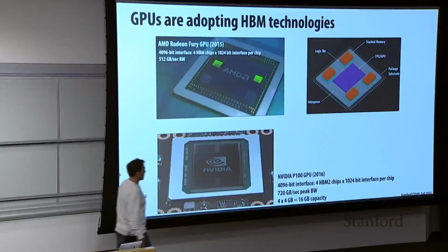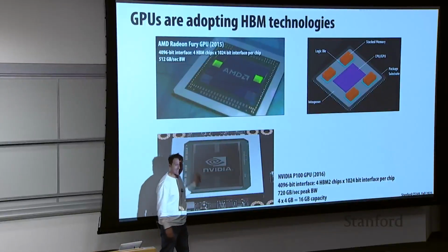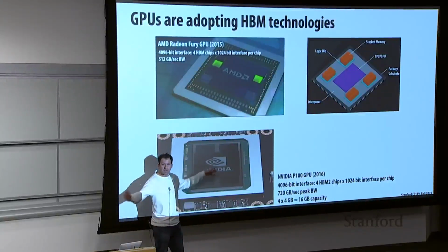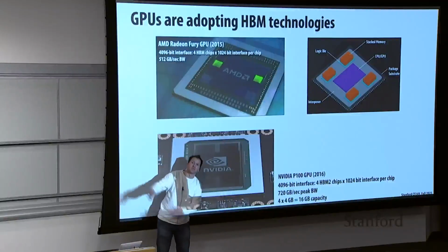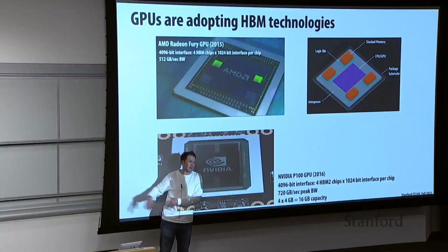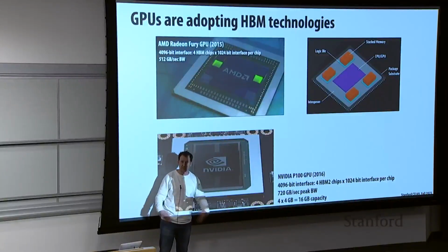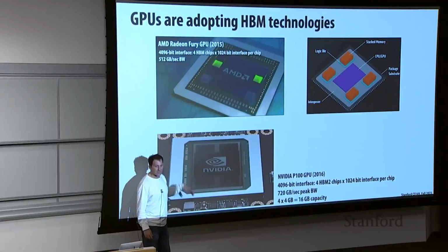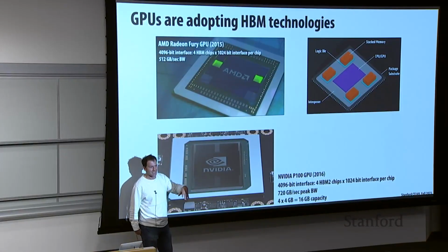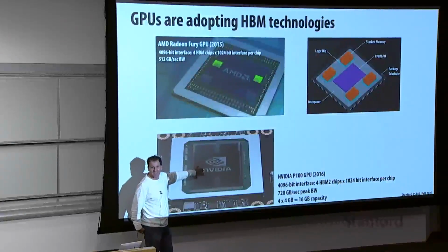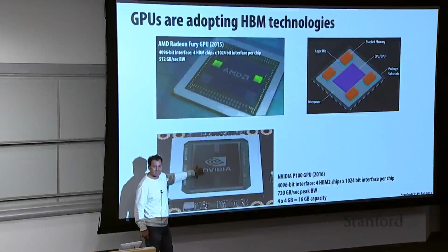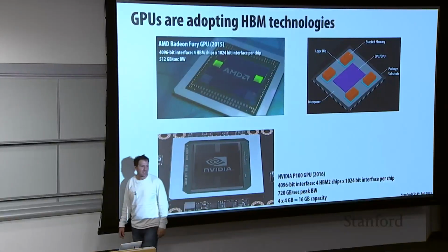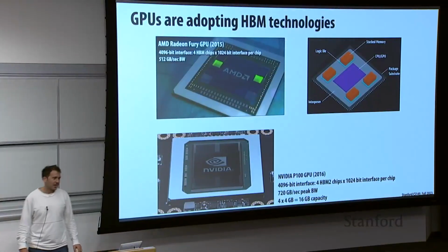Right, but this is a fixed amount of memory. So this is 16 gigabytes of memory only back in 2016. Now we're higher. And if you want large amounts of memory, then you have a traditional memory bus that goes out to DDR5 or DDR4, and you might have hundreds of gigabytes or terabytes of that. So this is a form of DRAM that is not the cache. There might be like an 80 megabyte L3 cache here. If you miss the 80 megabyte L3, you have access to, in this case, 16 gigabytes of about a terabyte per second of stacked DRAM.